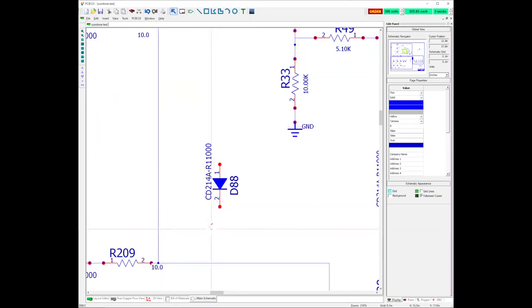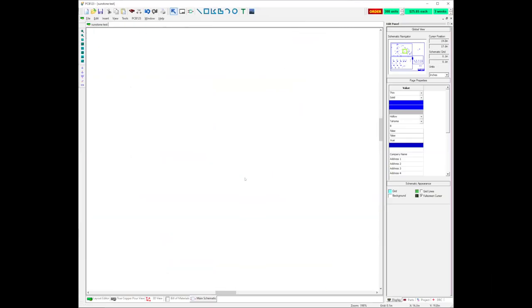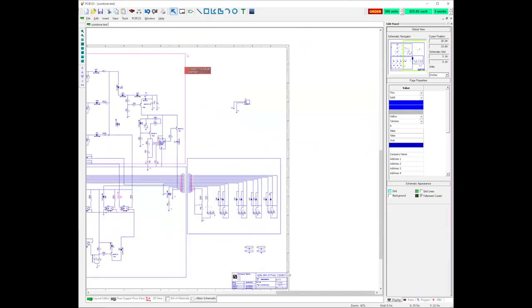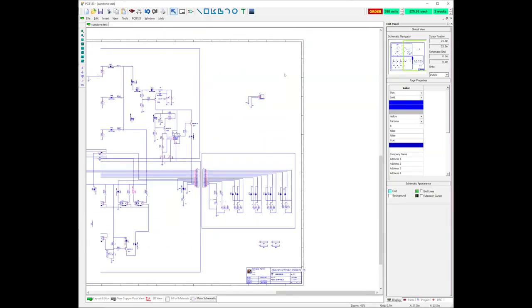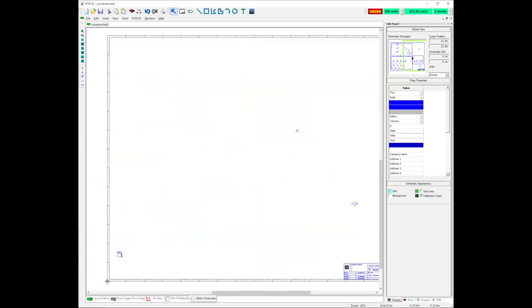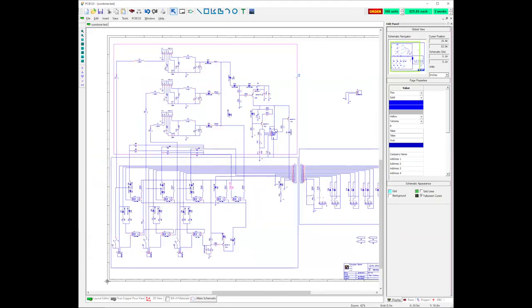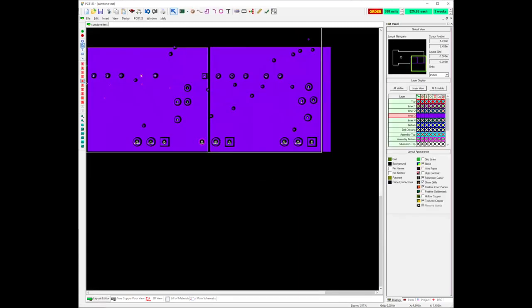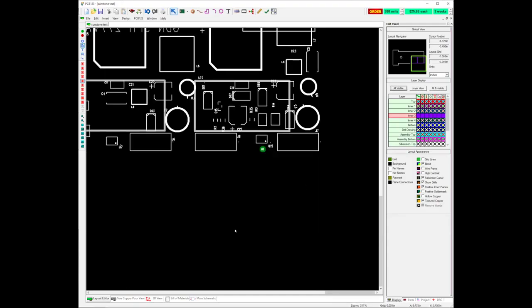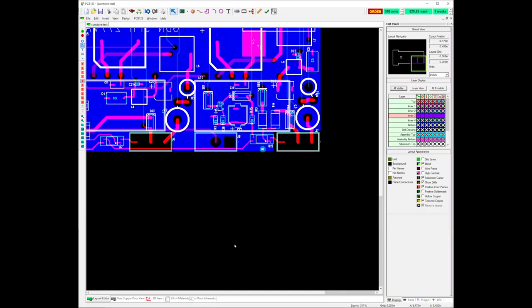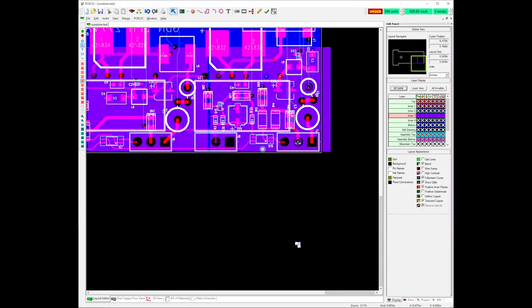And we looked and looked, and we could not figure out, because it was such an innocuous little thing. Finally, we discovered that these polygons that you can add create boundaries, and they basically lock up your design. My board still works just fine. It still does all the things it's supposed to do on this end, but in the schematic, these boxes, just don't use these boxes. That was a huge thing.